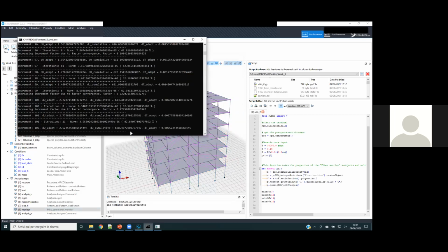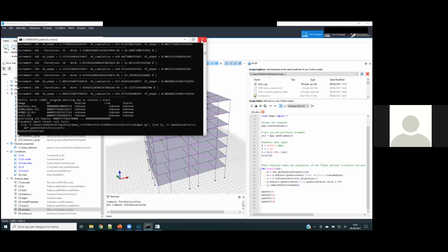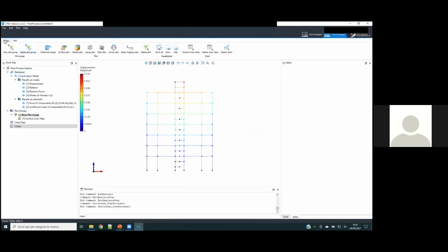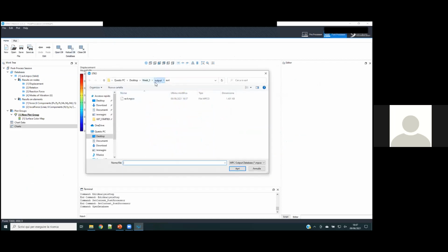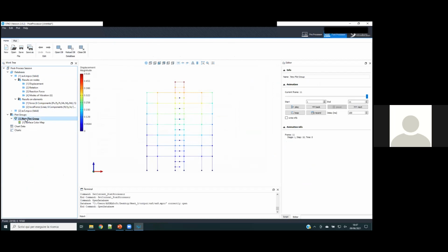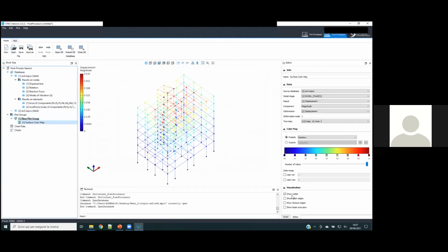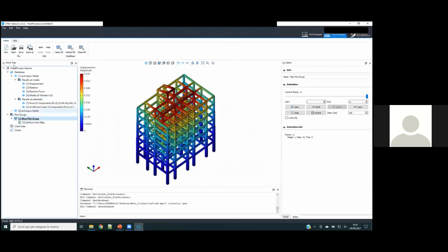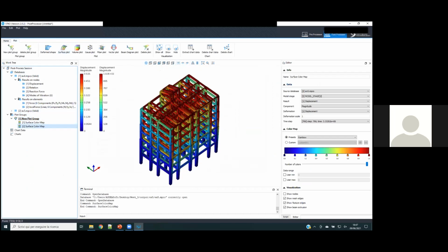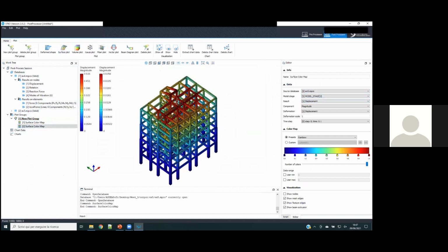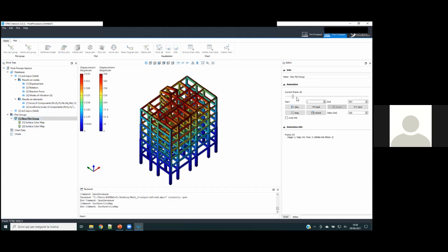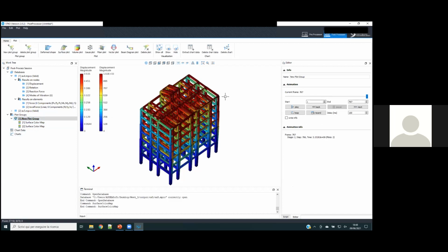Okay, so I'm just going to stop here now by pressing Control T here and just load the other database, to show you that you can load more than one database at once in your postprocessor STKO. And for example, let's say we go here and we change, we show everything, and we add a different plot, a second surface plot. Yeah, so this one is with the first database and this one is with the second. So if I go with model stage 1, which is the linear model, I have different displacement magnitude. One is linear and one is non-linear. But then I can see, for example,